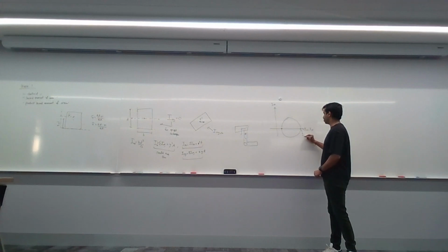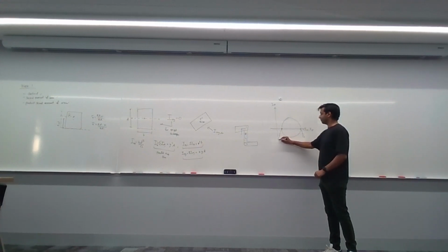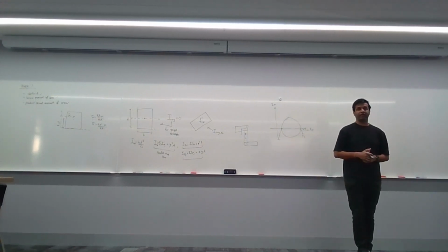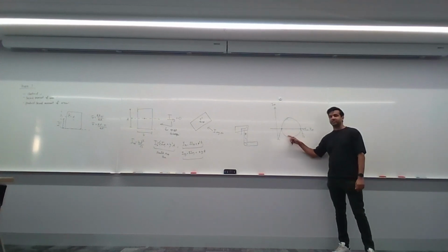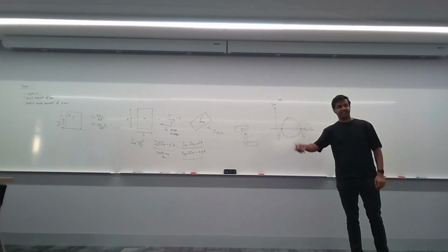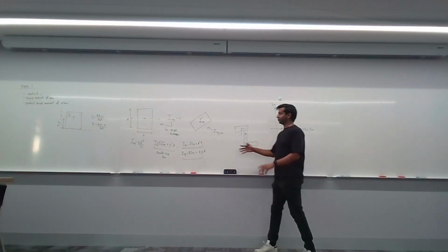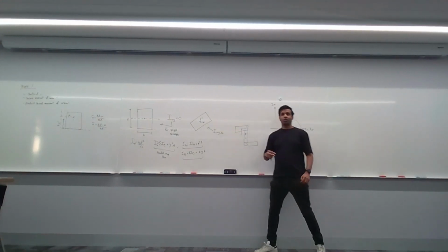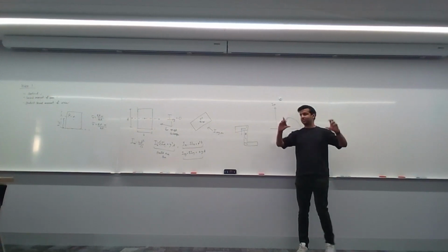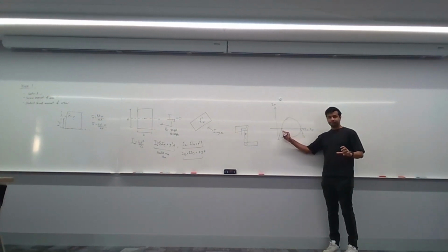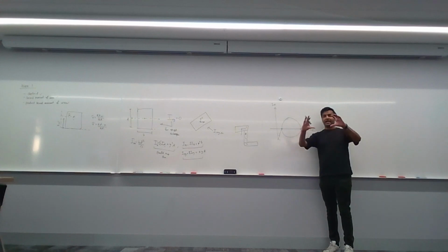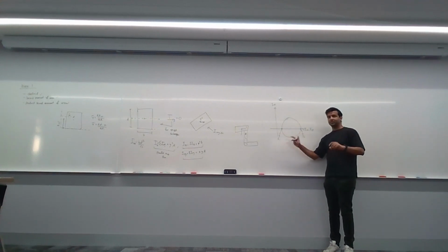Let's say this is I2, this is I1. Those are your principal second moments of area. And every point on this circle is every combination of Ixx, Iyy, and Ixy, right? So let's say, for example, you have this rectangle here. When the rectangle is horizontally upright, you start from here, right? And as the rectangle rotates, you start to go around the circle, right?